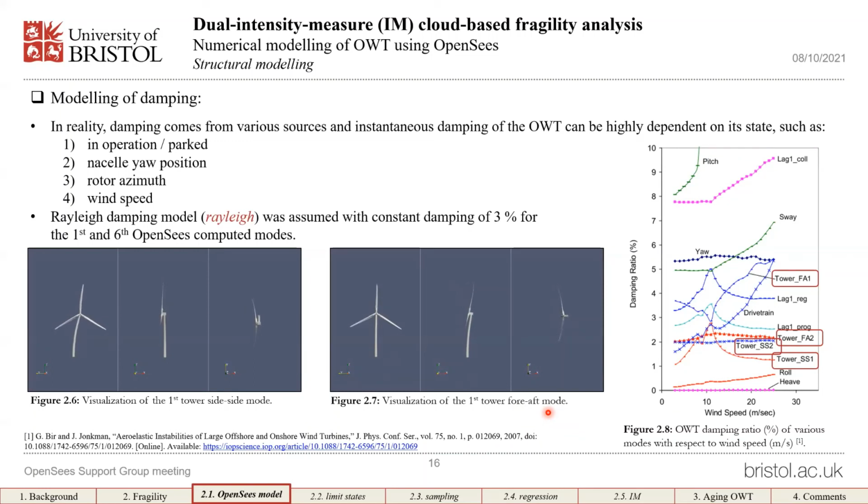Yes, but in reality, the side-to-side one occurs more, ahead of the fore-aft, because, for example, in bridges, you have longitudinal direction and transverse direction modes, but depending on your periods and so on, you can say which one occurs first. So you are talking about the mass participation of these modes. So basically, which modes are more easily excited by wind? First excited, yes.